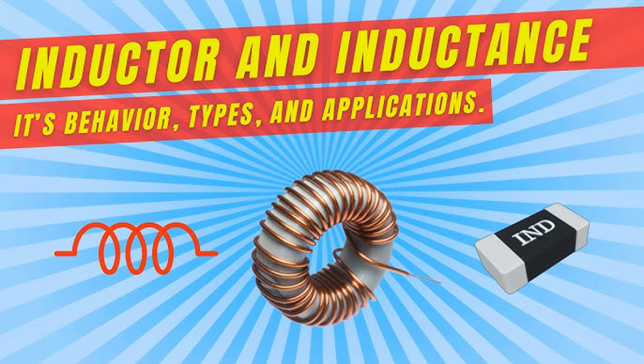RF radio frequency filtering. Application. Inductors are used in RF circuits to block or attenuate unwanted frequencies while allowing desired signals to pass. This is essential for maintaining signal integrity in communication systems. Example: in a radio receiver, inductors are used in combination with capacitors to create tuned circuits that filter out all but the selected radio station.